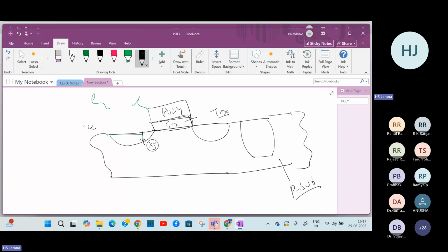They will not give these kind of things. What is the junction depth? What is this geometry? They will not tell. And in a gate oxide, whether it's purely silicon dioxide, normally ours is not silicon dioxide. It's a nitrated oxide.